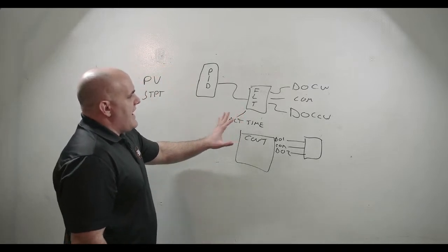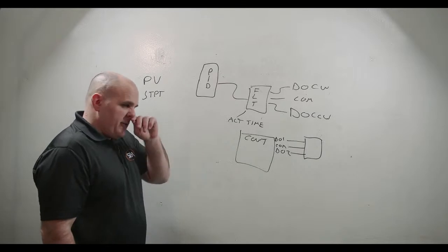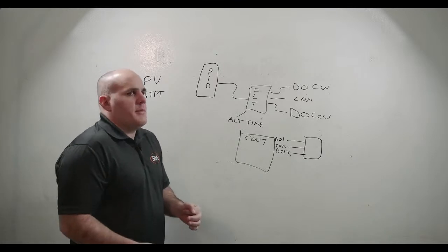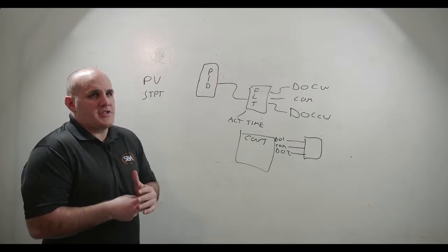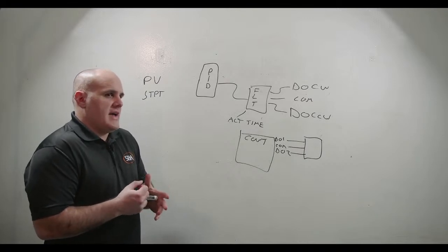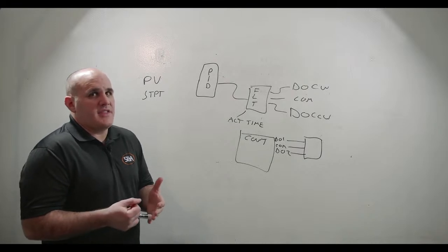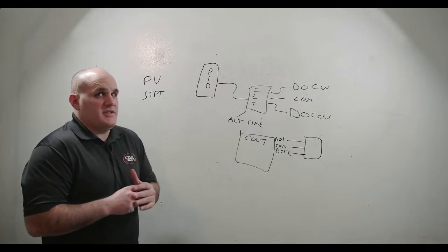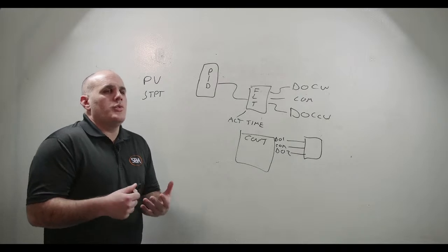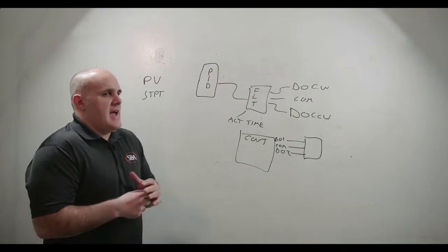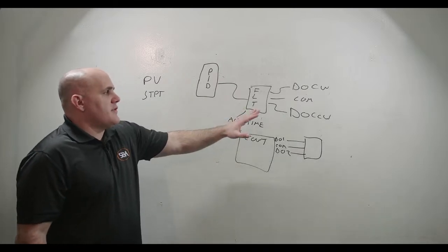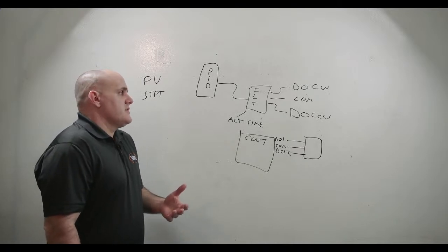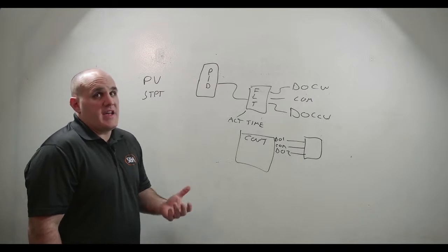Okay, so you've got this actuator, and the actuator itself has the ability to drive it clockwise and counterclockwise. But the problem is that unlike a proportional actuator, where all that timing and everything is built into the actuator, without getting into the specifics, you don't have that built into the actuator. So the actuator itself has no real way of knowing where it's at. And because of that, when you drive your DO to hit 50% or 60%, it's a calculated value. So the floating block kind of keeps track of where the actuator used to be.